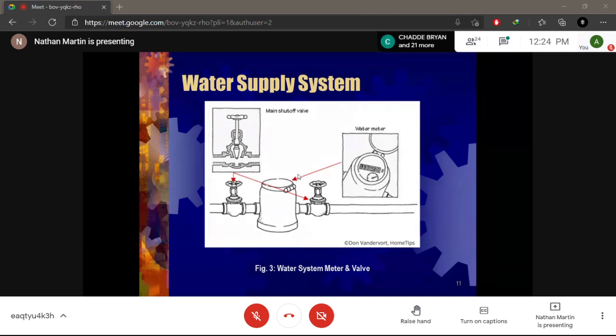Because after a period of time, because of the water and the chlorine in the water, your pipes will start to rust, compared to that of your PVC. But with the PVC, after a period of time, if it is not properly buried and is exposed constantly to the sun, it becomes crystallized and then it bursts and starts to leak, right? So they both have their advantages and their disadvantages.